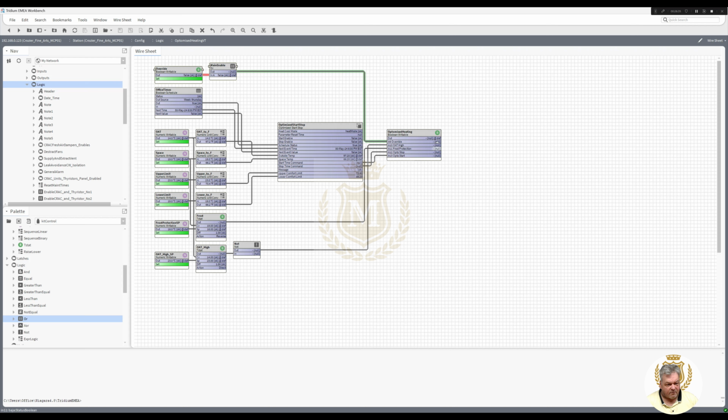And then from that output goes to your heating, so your boilers or whatever, or your VT. Now if it's just VT control, you would have a space temperature sensor, and you would have a control variable set point.